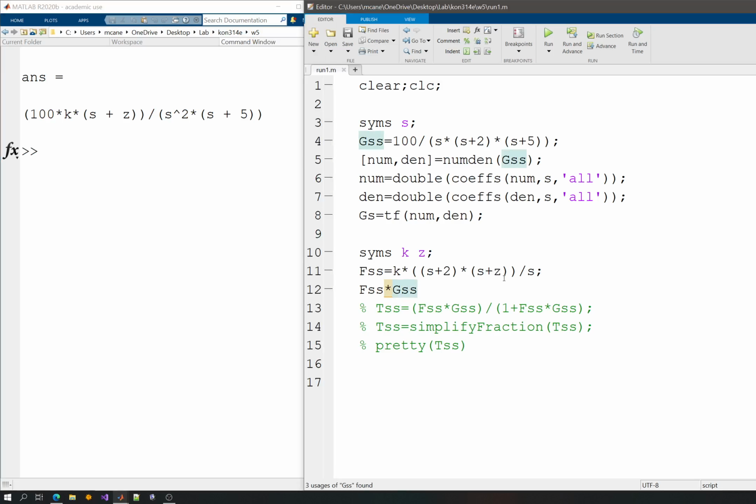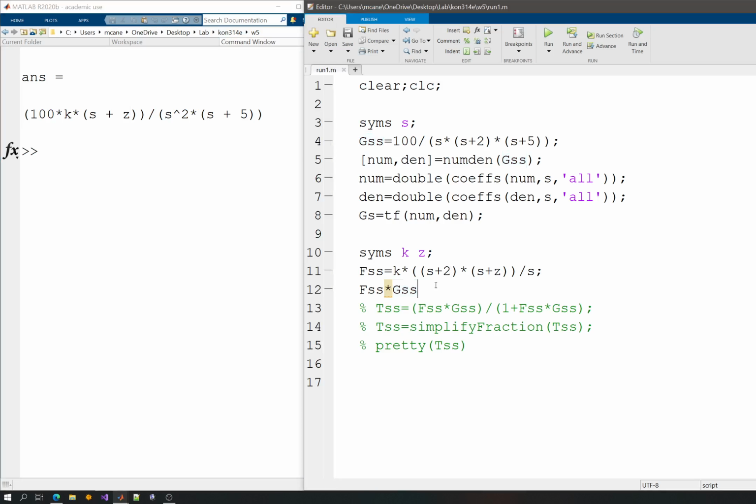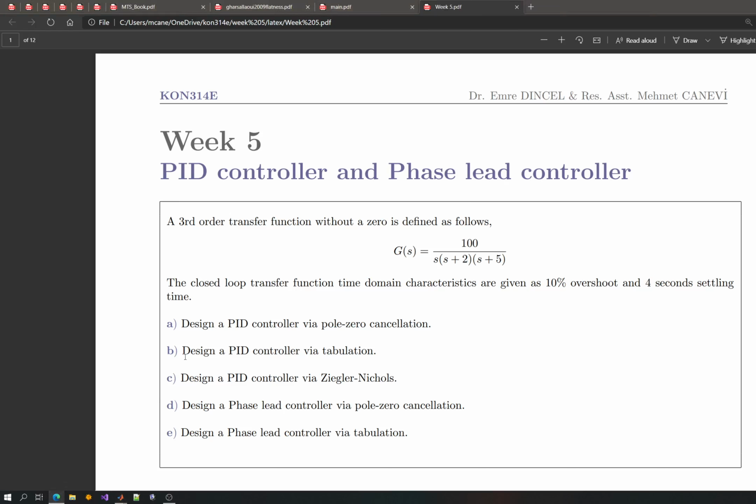The algebraic approach uses equations to solve that. The root locus approach, where the name implies that too, will use the root locus angle condition, especially for being on the root locus. And if it's on the root locus, it's reachable with a k, and then you can go ahead and determine the k. So 2 steps, 2 conditions, and 2 unknowns. You can see that easily it's possible to solve for that. Now, I also should maybe look at that, and it wants a 10% overshoot and 4 seconds settling time.